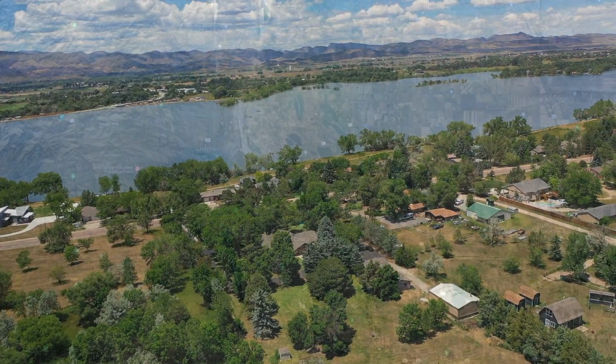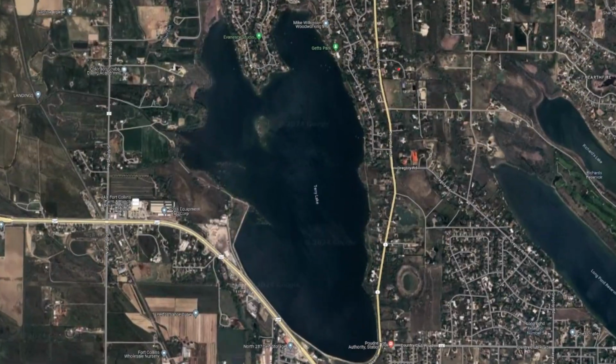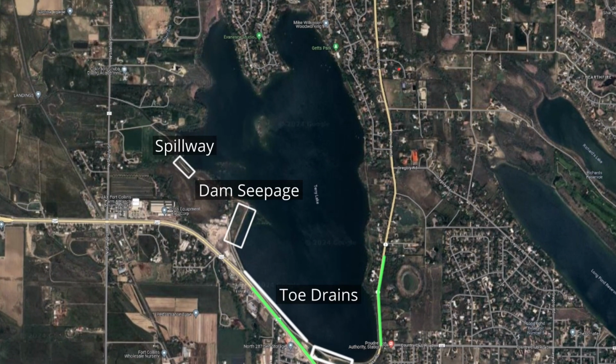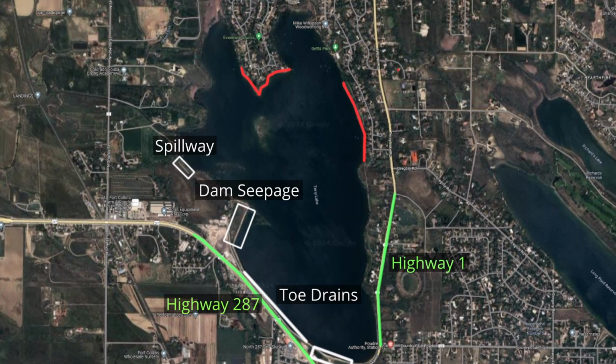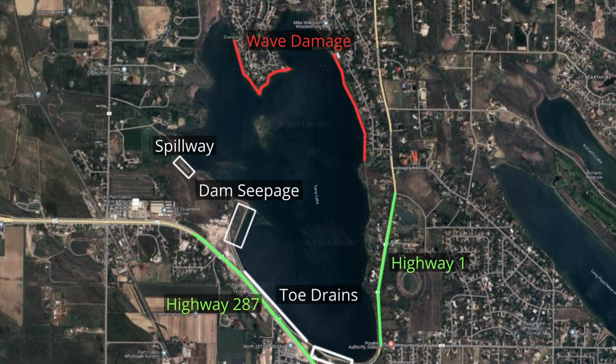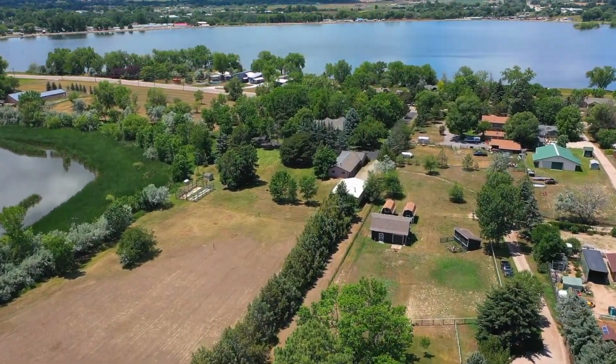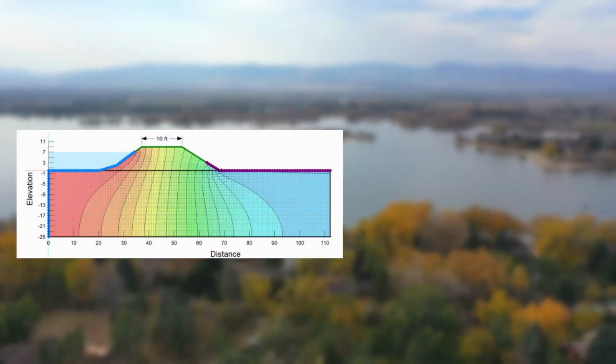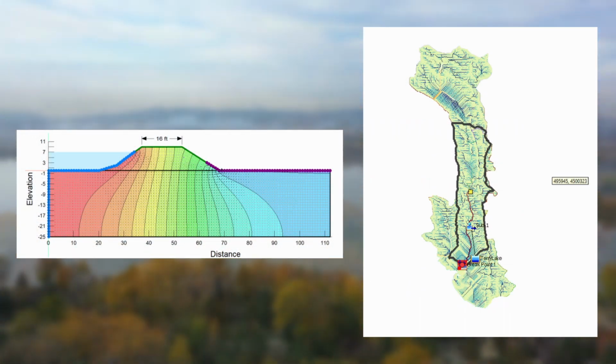Our first objective was to identify key locations around the lake, being the locations of the spillway, dam seepage, toe drains, and neighboring highways. The locations of wind-generated wave damage were also identified to be used at a later date for erosion analysis. The first major step towards establishing remediation requirements was to create geotechnical and hydrological models of the areas of interest.